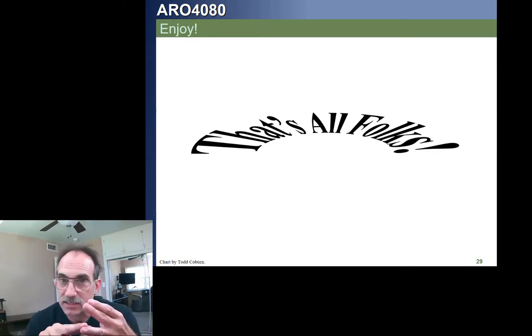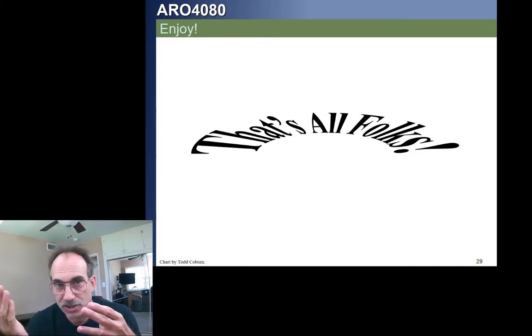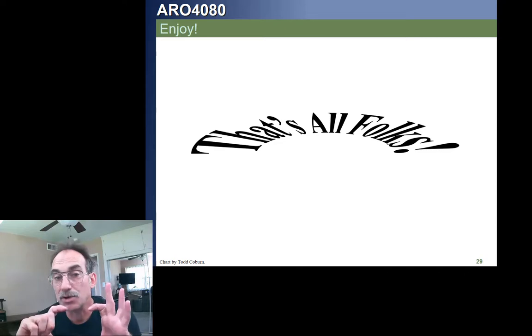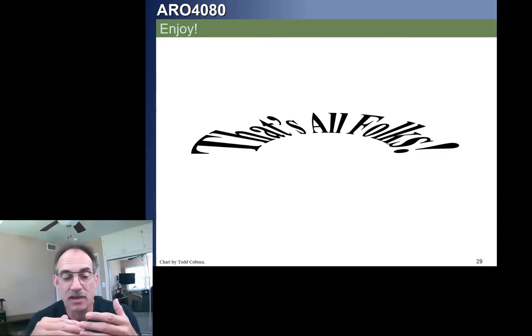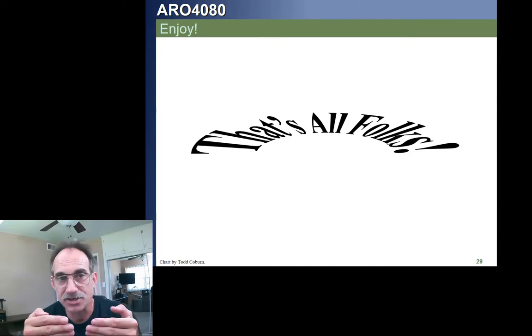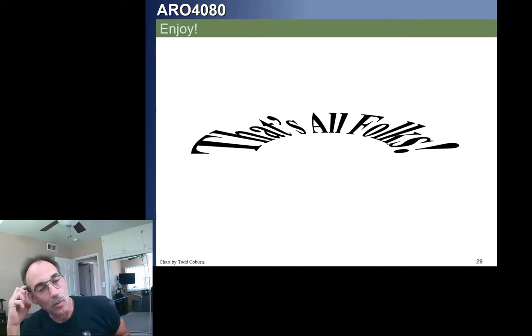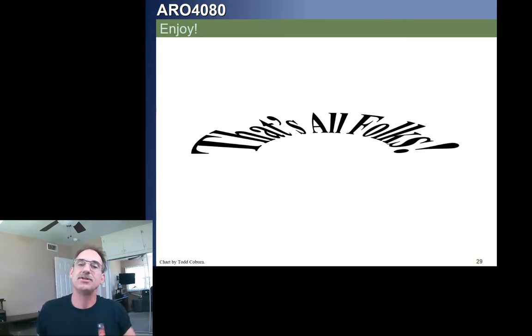For any 0 constraints, we're going to take advantage of the homogeneous system and eliminate those rows and columns from our matrix to get our reduced global stiffness matrix. If we have any enforced displacements, we're going to have to rewrite one of our equations to decouple our equation so we can reduce down one more, and then that will allow us to solve the reduced system.